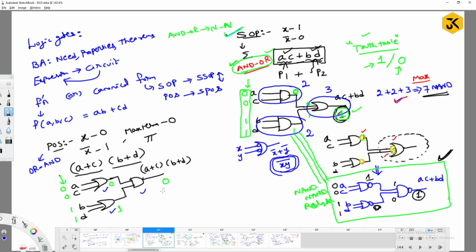When you get this, you simply do the same process. At the outputs of the OR gates, put the complements, and as you put the complement here, if you put a complement at the input of the AND gate, they are going to be cancelled out. If you put it here also, they are going to be cancelled out, right? Now this particular representation can be represented again in the form of a NOR gate, right?